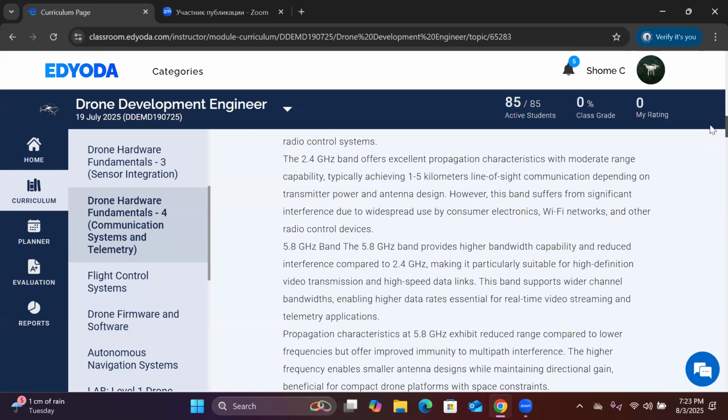So for that, I need to increase the RF transmitted power. Now, every wireless LAN module, whether you take it from any manufacturer, will have an integrated RF transmitter. So it will have an integrated power amplifier. That RF power amplifier will be able to transmit the power up till a certain wattage value. Say if I take 30 dBm or 1 watt, till 1 watt that wireless LAN module will be compatible to transmit the RF power, thereby putting my range till 5 kilometer with an endurance of say around 30 minutes or 45 minutes, for example.